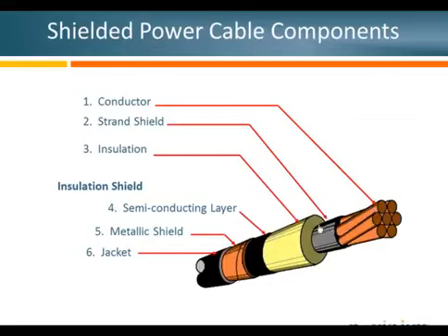So you have the conductor and the conductor shield, and then the insulation, which insulates the high voltage on your conductor from ground on the outside, which consists of your semiconductive insulation layer of the insulation shield and the metallic. So your insulation shield is comprised of both of those layers, the semicon and the metallic. And then you have a jacket, typically, on the outside of the cable.